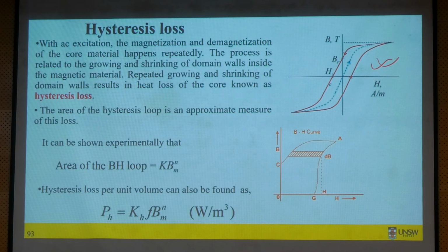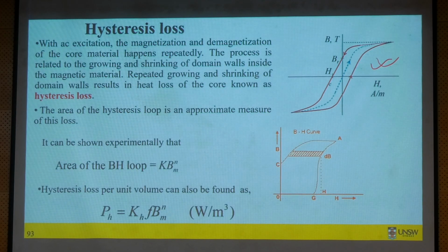So if you operate the motor, a PM motor, under no load condition, you can measure how much power it is taking. Okay? The no load means the motor is rotating freely. You're supplying voltage and current. The motor is spinning freely, not coupled to any mechanical load. So in that case, you may think that it should not take any current, or any loss.